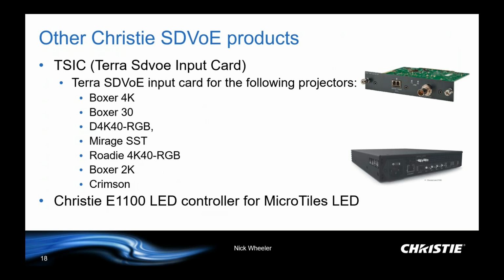There are other SDVoE products that we have as well. One of them is the TSIC card, which we use for a number of our projectors. It's an SDVoE input card. So you've only got a single fiber connector on the front there, LC-LC. But you still get everything else. You can still control the projector from a laptop and log into its web page to be able to control it and so on.